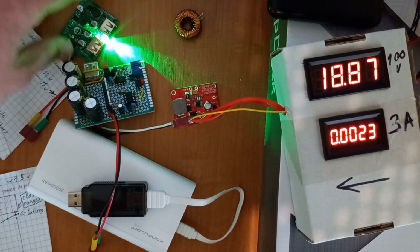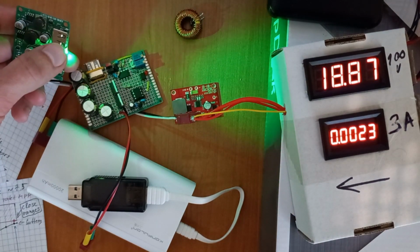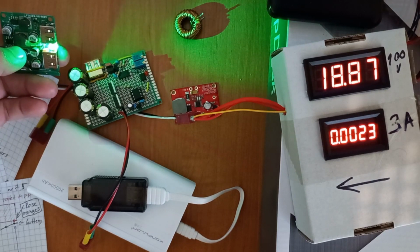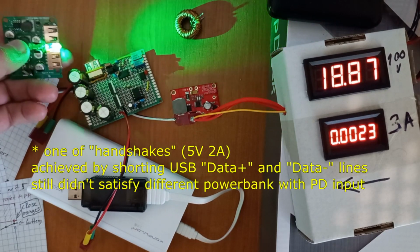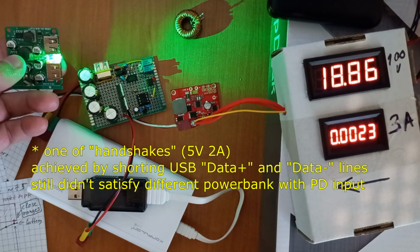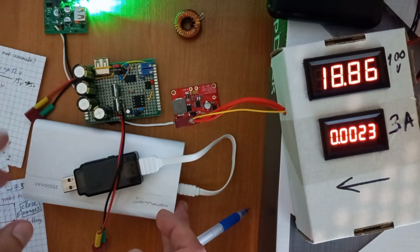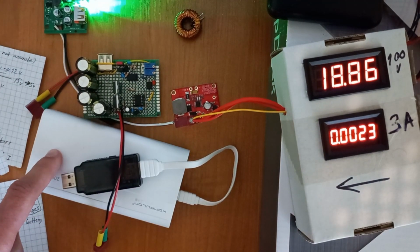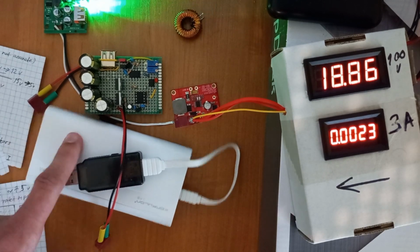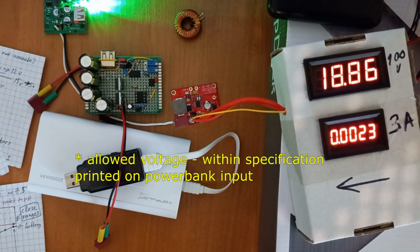Some extra notes on power banks with power delivery and this stuff. Such power banks may not want to consume energy without a handshake and act pretty weird. I tested several different power banks and had really different results. This one with QC works, which is very comfortable for me. It works fine without handshakes. You can actually feed it with pretty much any allowed voltage and it will just accept it.